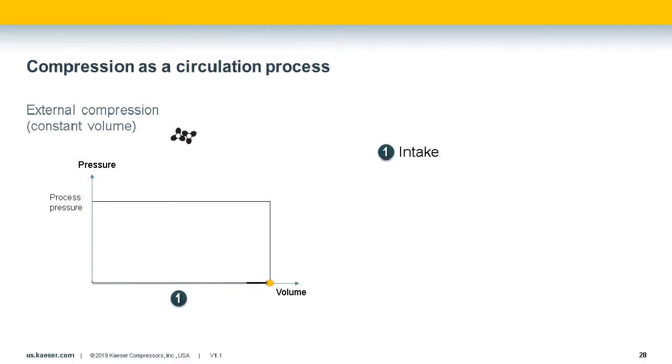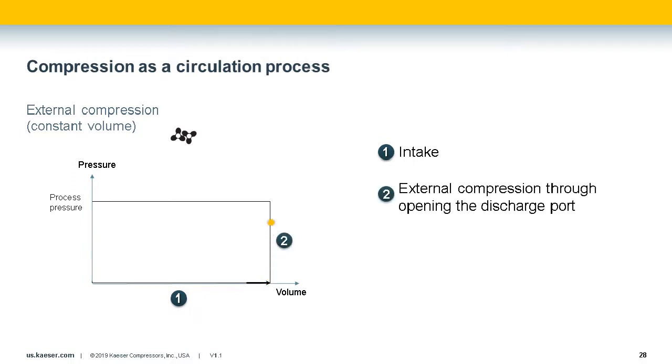The rectangular area in this diagram is spanned by the flow rate through the compressor and bridged by pressure as a difference. This represents the compression work. So if we go 1 to 2 to 4, there we have this rectangle which represents the work done by a PD blower. The pressure represents a force and the rotation of the rotors displaces the volume at that distance.